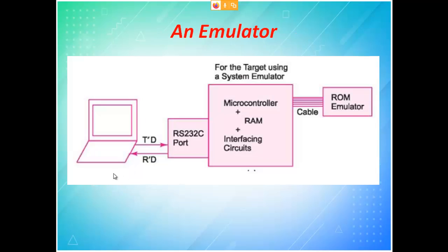So finally, this is your system where you sit and do your program. Everything is being generated by the target emulator. This emulator part has an inbuilt microcontroller and such things. I told you, you don't have the physical sensor, but I know what the input will be, so I will generate it with the help of my microcontroller. That microcontroller generates what the sensor output would be. Don't confuse this with the microcontroller in your embedded system. This is not that microcontroller. This is the microcontroller inside the emulator. So emulator manufacturers are there.